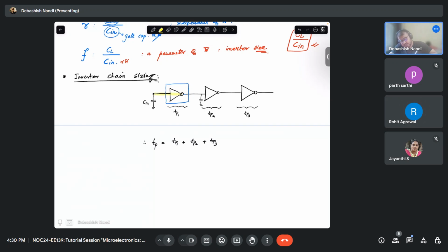There is basically something called critical path. If you have multiple paths, you only add the delay of your critical path from input to output, which contributes to your maximum delay. That is contributed by adding individual elements. If you work in any project management company, for a project there are multiple sub works.